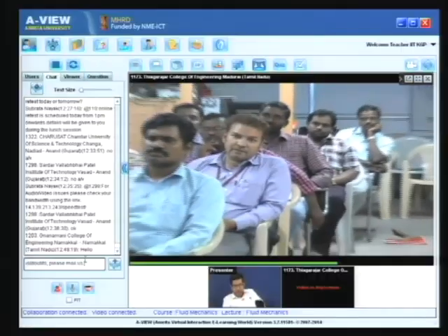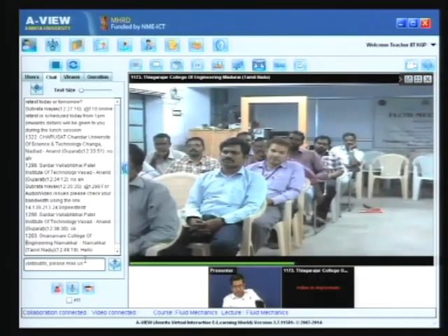Skin friction is the manifestation of the shear stress. Skin friction is one normalized expression of the shear stress at the wall. Skin friction coefficient is usually used by engineers in practice, but actually it is the shear stress at the wall, tau w by half rho v square, and shear stress at the wall is very much related with the boundary layer thickness.